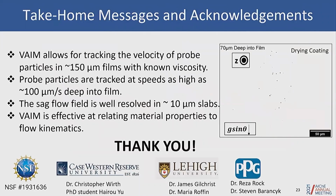So with that, I would like to give some take-home messages and acknowledgements. VAIM allows us to track the velocity of particles in a film about 150 micrometers thick with known viscosity. And these probe particles were tracked at speeds as high as about 100 micrometers per second. The sag flow fields were well resolved in a 100 micrometer slab. So finally, VAIM is very effective at relating material properties to flow kinematics.